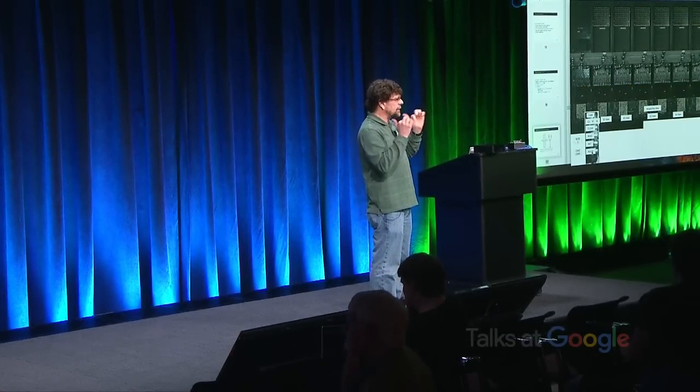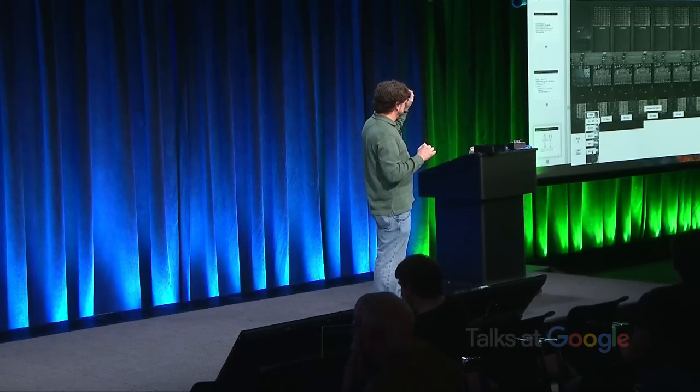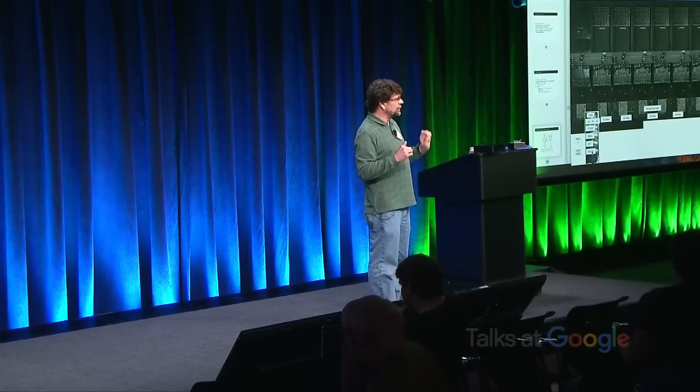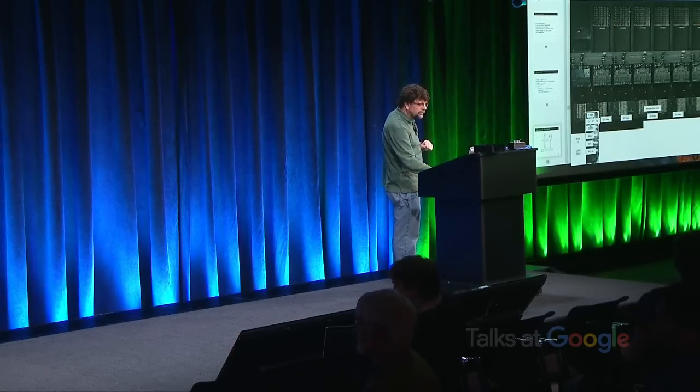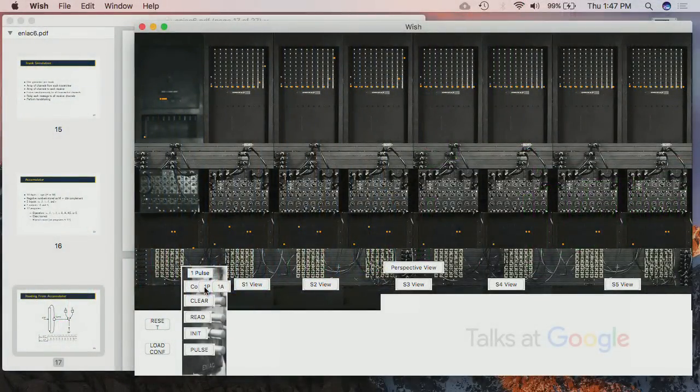And what I'm going to do now is go through step by step how it transmits from one place to another. The additive output's going to go into one of the other accumulators and the subtractive into the other. So I'm going to simultaneously be computing the sum of 15 and 27 and the difference of 15 and 27. So let me switch the clock now to the single pulse mode. And we now begin this sequence.